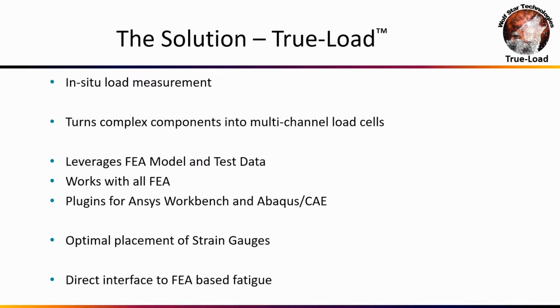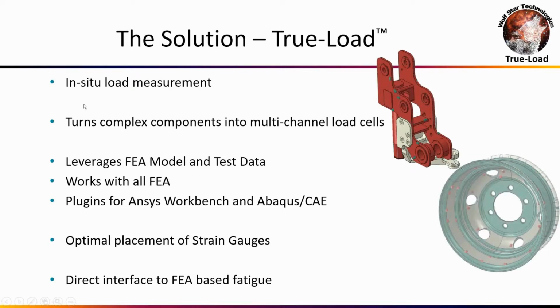So the solution here is TrueLoad. TrueLoad is doing what's called in-situ load measurement. So in-situ means in-location load measurement. So we're going to turn your components into multi-channel load cells by leveraging the FEA model to work with the test data. We can work with any FEA.